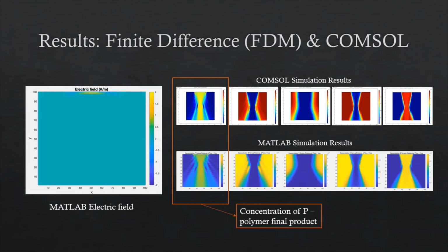In the case we simulate, one focused laser beam enters from the top, as you can see in the electric field propagation. To reduce the time needed, we simplify the case. We first get average intensity during 20 light cycles using EM wave simulation. Then the intensity information is passed into reaction and diffusion codes, while assuming the average intensity is constant during 1 microsecond. With concentration simulated, average intensity during the next microsecond is recalculated. And we repeat this process 1,000 times to get concentration plots and data during 1 millisecond.